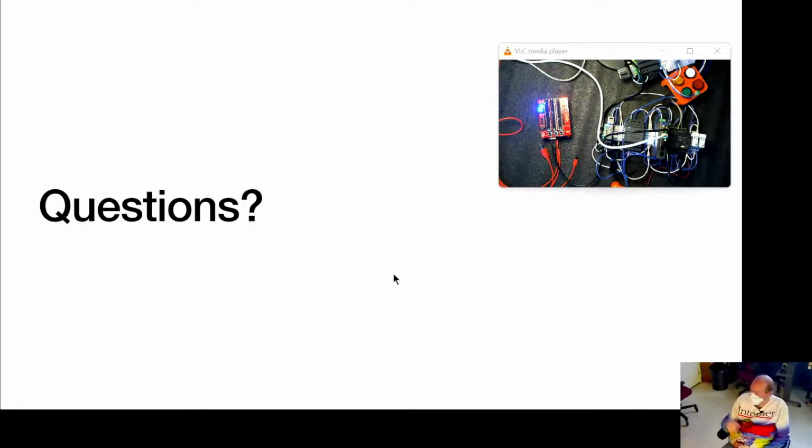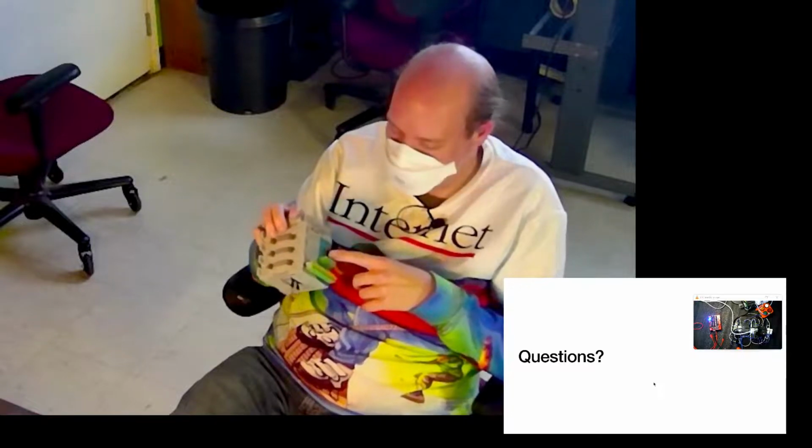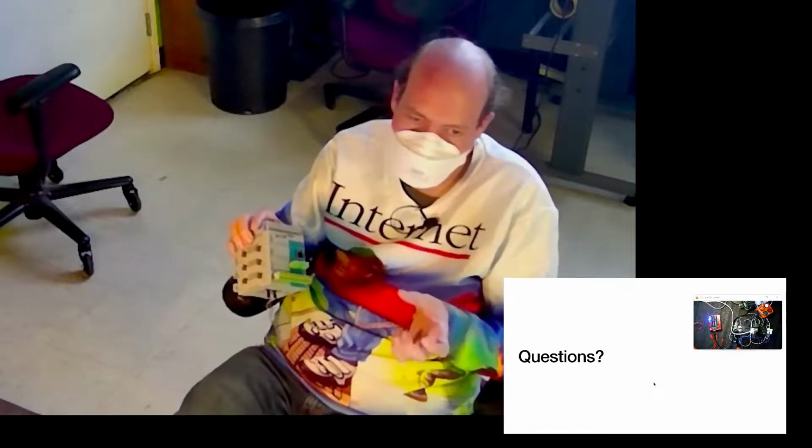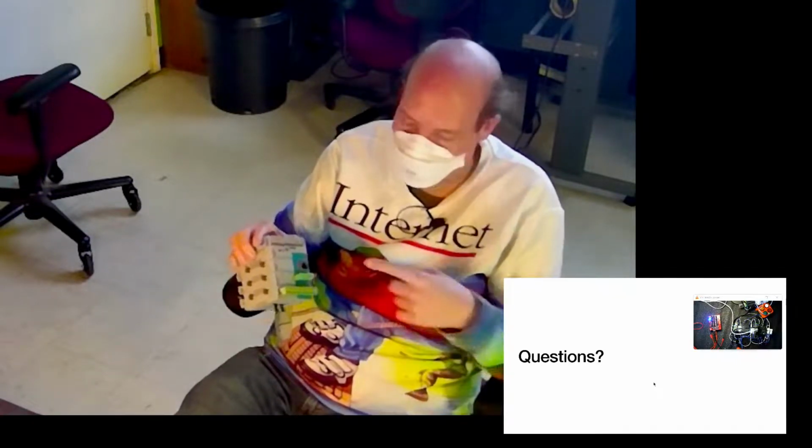Another example of Python is this guy, the P1AM. The P1AM 200 you can program in CircuitPython. Have you worked with CircuitPython before? Yeah, so to explain to everyone else, CircuitPython is another embedded programming option for these where you plug in the device and it shows up as a drive and you edit your main.py or your other py files, and when you save them, it reloads them and starts running your changed code in the controller itself.